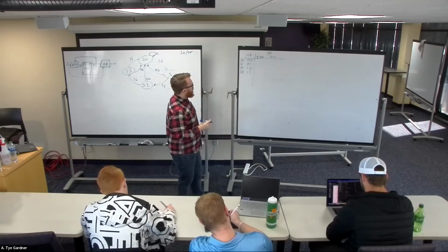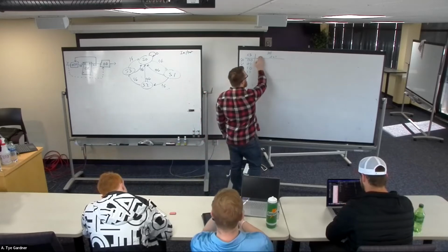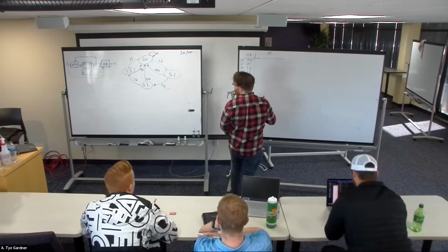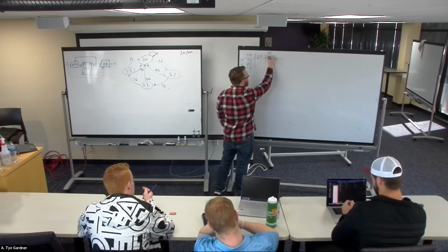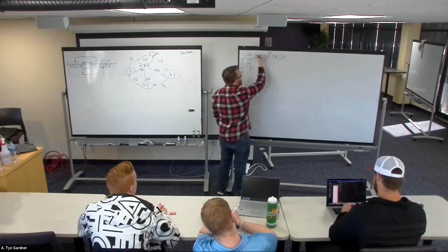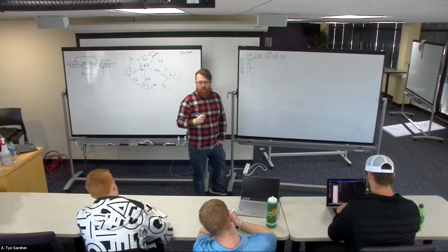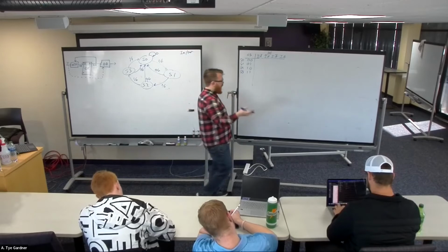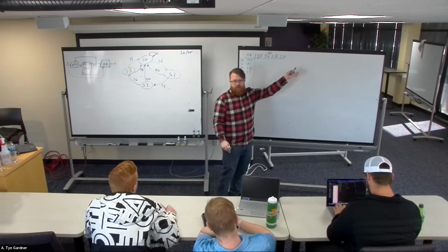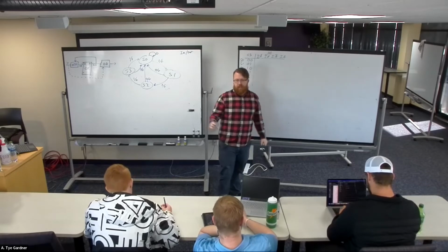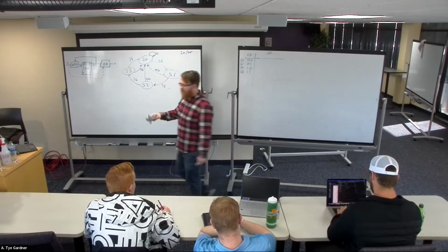Now, I'll try and give an example before I do. If you had 2 inputs, say that I have inputs I and A, then I would need to start labeling all of them. I would have IA, and this would be 0 0, 0 1, 1 0, 1 1. That's how you do that. And now I would have all possible combinations. However, for now, we only have one input, so we don't have to worry about that. This is why many inputs start to get really difficult, right? It gets really hard to deal with 5, 6, 7, 8 inputs, which in the case of the calculator, we're going to have like 16, I think, inputs, which obviously we can't do by hand, which is why VHDL is a useful tool.